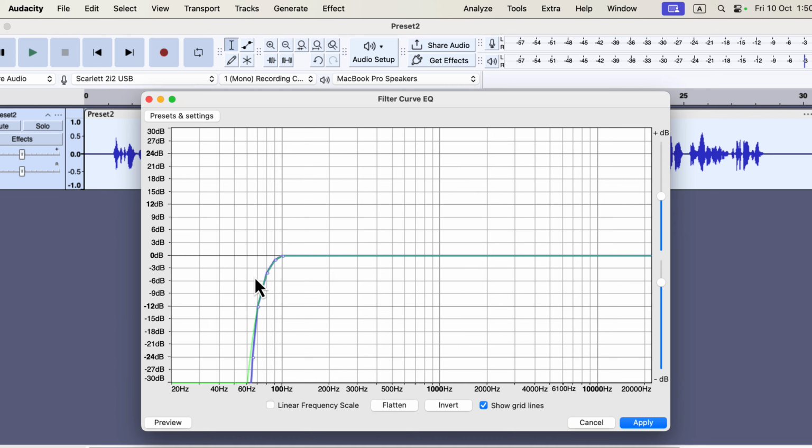However, there can be some noise in the low frequency areas. A low roll-off can take down such noise if there is any. This roll-off has been started from 100 Hz. I will drag the dots so that the roll begins from 80 Hz. If you click on these lines, such dots appear. I am cutting off frequency below 80 Hz, which is also called a high-pass filter. This removes low-frequency noise, like hum or vibration, that doesn't exist in human speech.